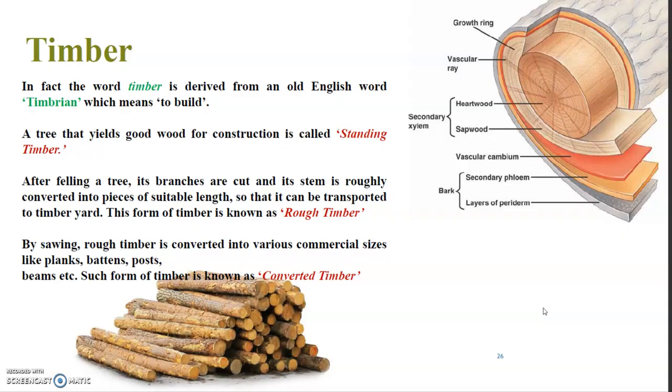So why do we need to reduce it? Once you reduce it, only then can we use the timber for further engineering processes like cutting, sharpening, edging, polishing, or whatever it may be. If you don't reduce the moisture content to a certain level, it would be very stiff timber, it would keep attracting moisture on its surface and in its mass, and it may allow fungi growth on its surface.